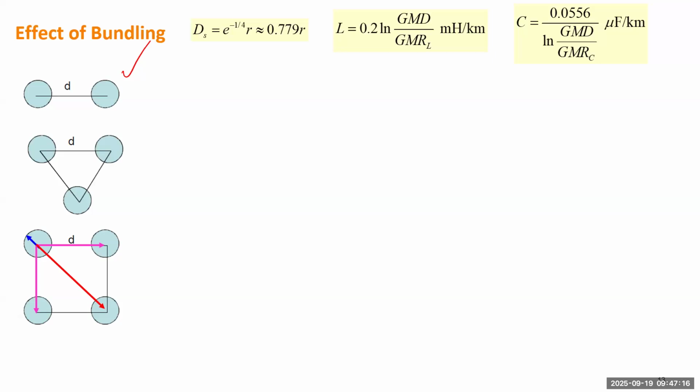how are we going to calculate the GMR for both inductance and the capacitance? So the first one is easier. First one, because the radius is defined, if we use any conductor as reference, there are 2 distances we need to consider. So those 2 will be here. We just calculate the product of the radius of the first one and the distance to the second one.